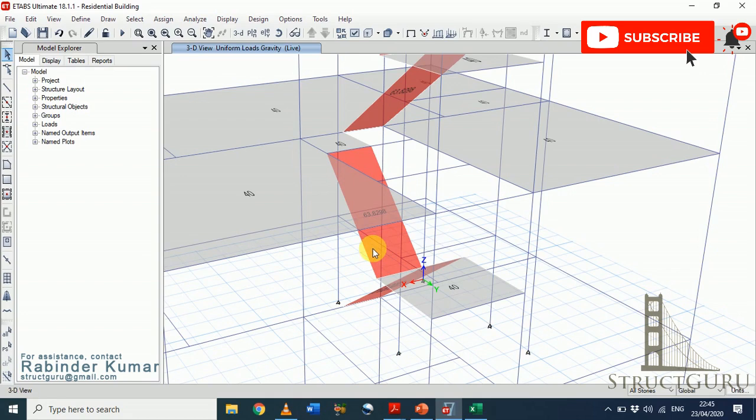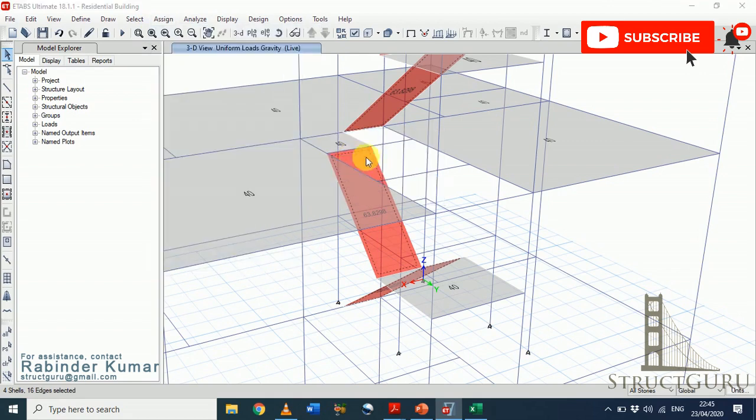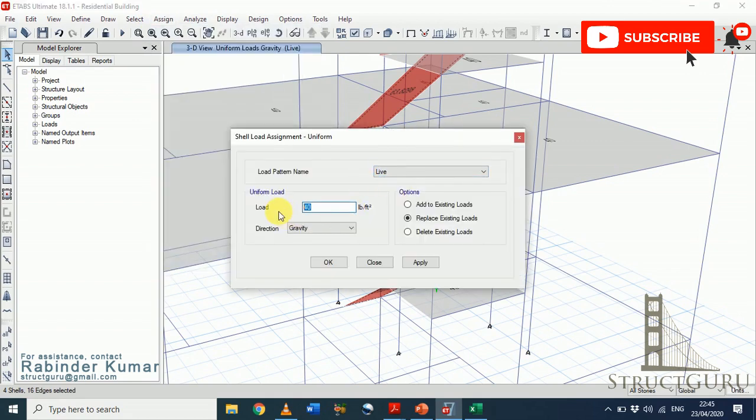Choose the staircase area. Go to assign menu, shell load, uniform load. So the live load was 60.